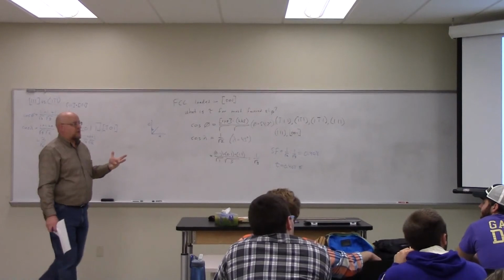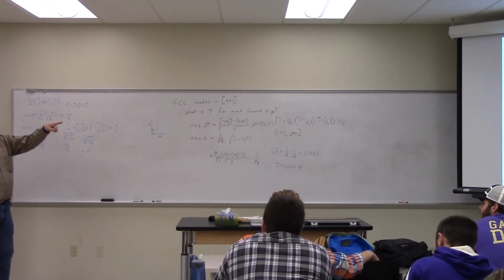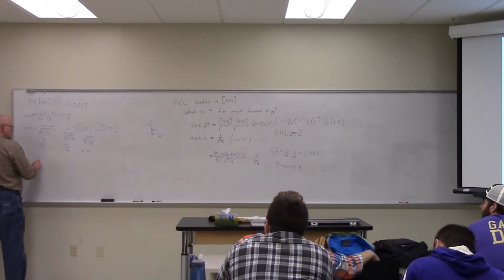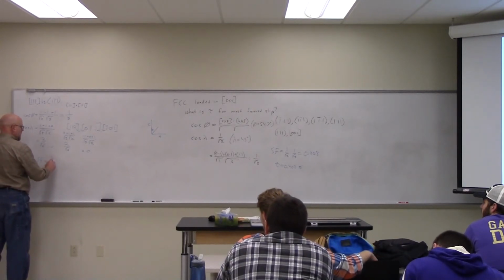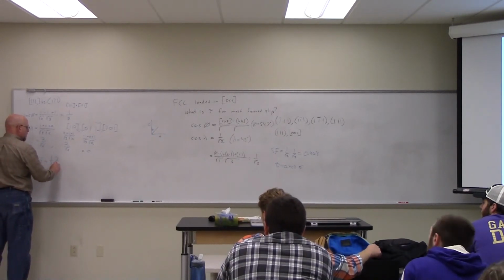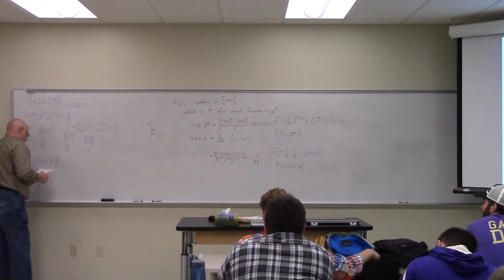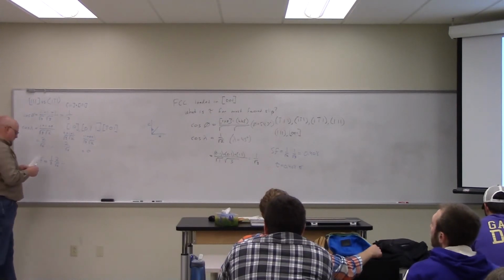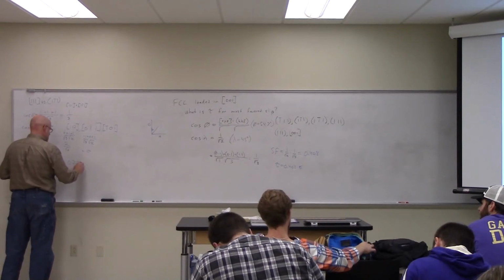So in this particular configuration, if I pull in the 111 direction, that one's dead, the other two are equally alive, and my Schmid factor is 1/3 of 2 over root 6, which is something really small. I don't know what that is because it's not the most active one. Oh, it is. Yeah, it is. Which is 0.272.